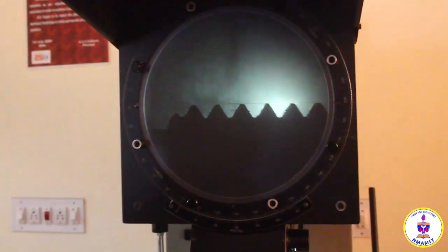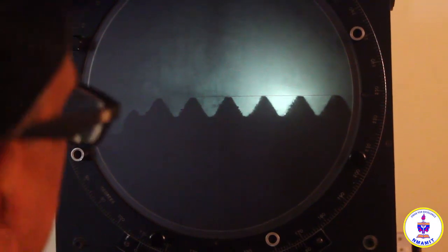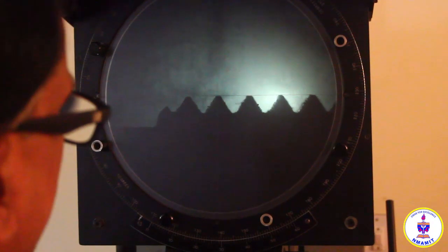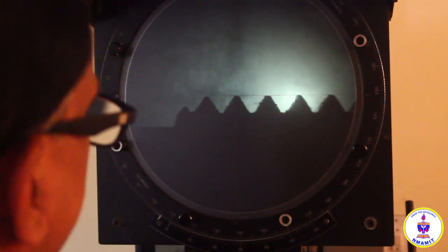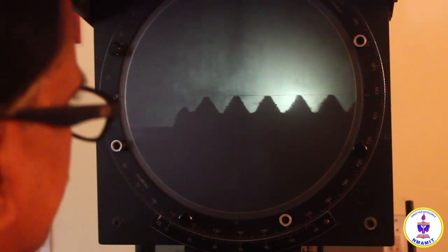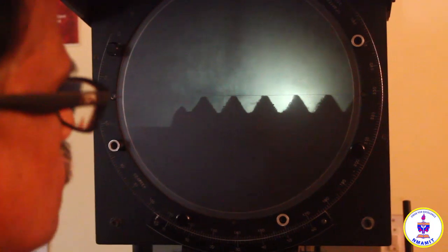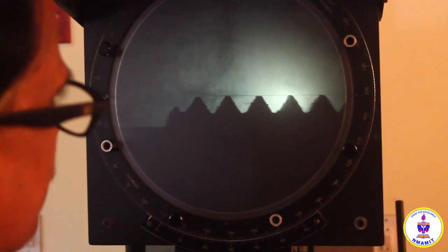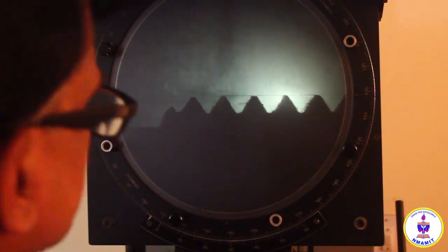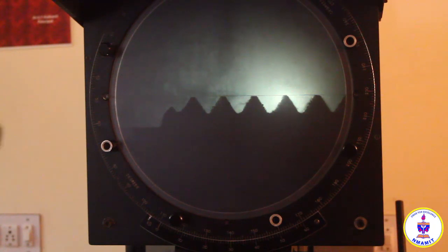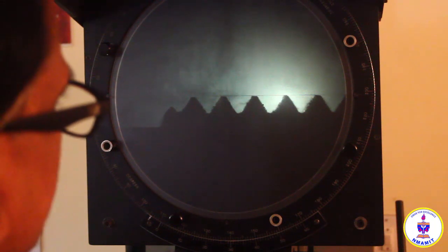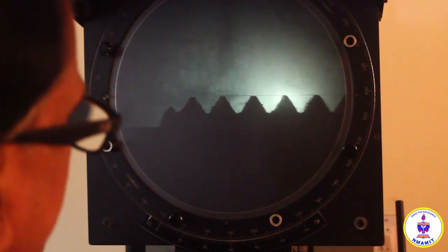So for that, now the measurement is on the other micrometer. Here the shadow can be moved longitudinally by moving this micrometer. So pitch is, say, from crest to crest or root to root. Say a reading on one thread and move it to the next thread here. But since the crest of the thread is not very sharp, it is either a radius or a truncated crest here, it is very difficult to position the cross line exactly at the identical position.